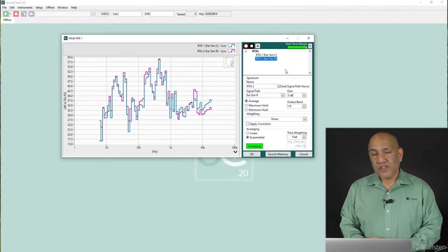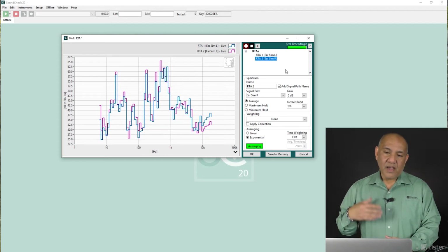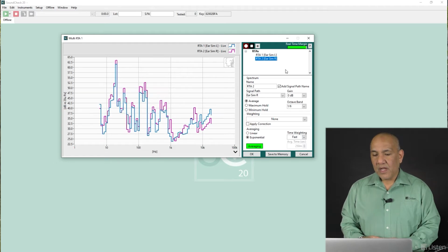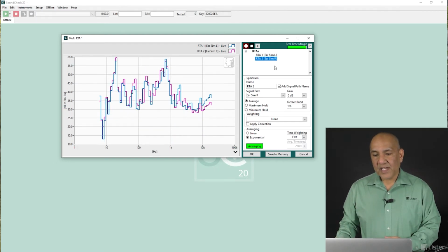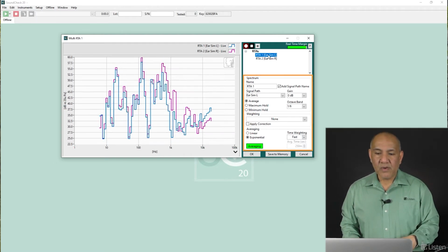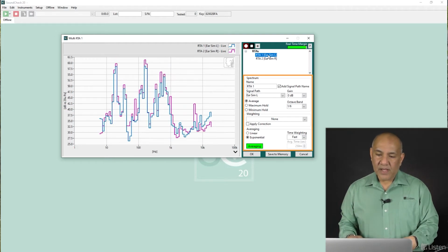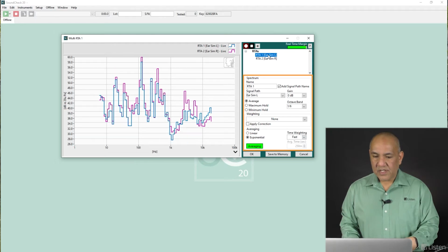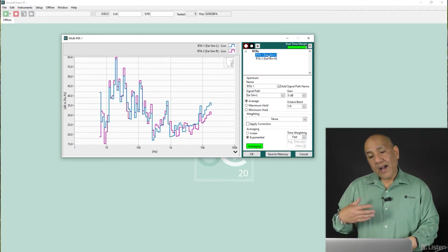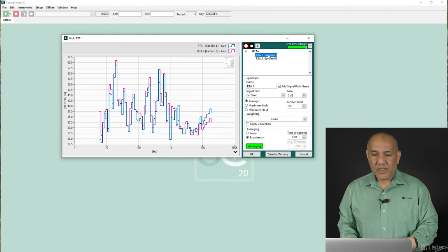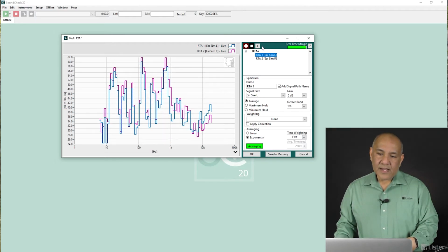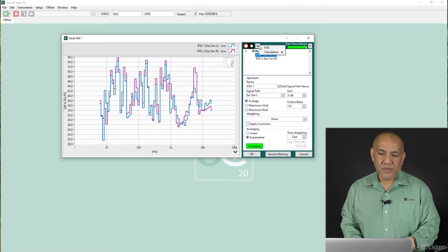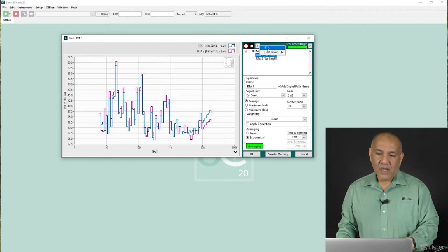Okay, so let's look at the multi-RTA. Currently, I have the instrument open, and you'll see I'm monitoring 2 input channels. Each input, as I click on it, has settings below. This defines what my signal path is, how I'm averaging, what my octave resolution is, and weighting. I can save each input with unique settings, and I can add as many inputs as I want by clicking the plus symbol at the top, and you'll see I have RTA.